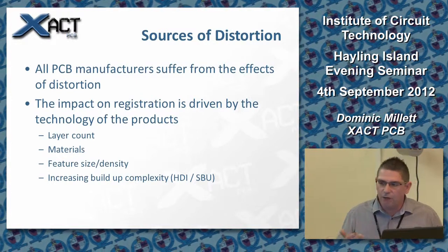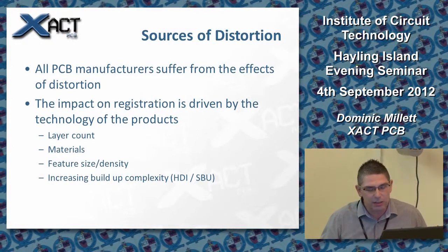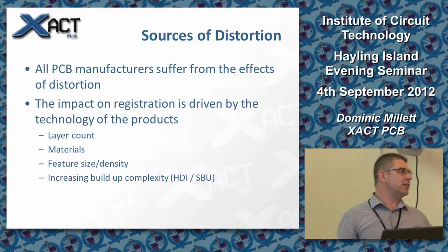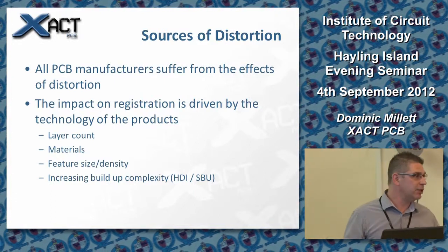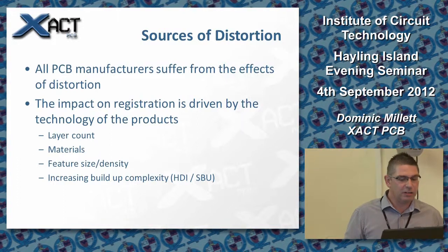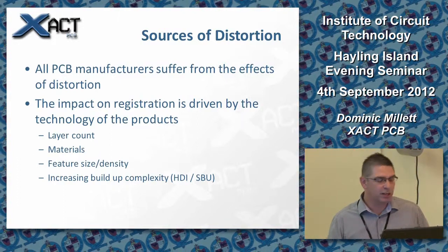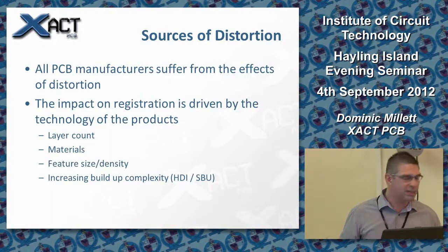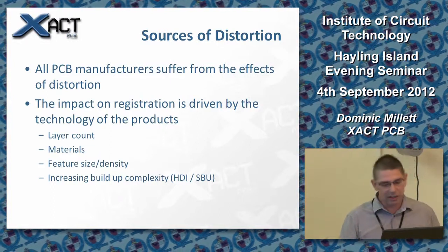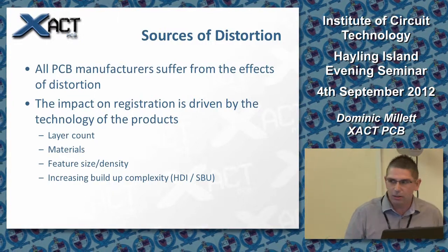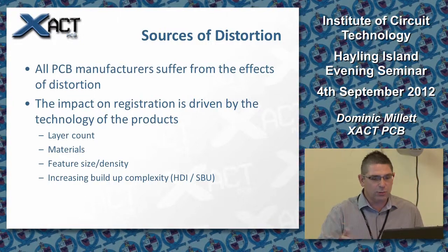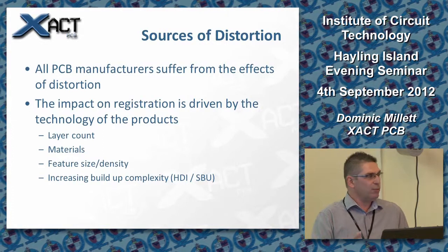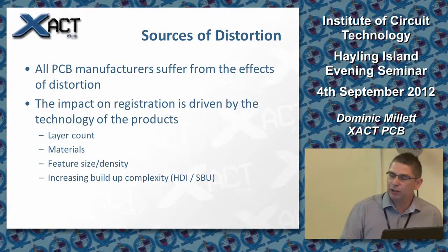Typically, we've seen a lot of designs getting ever more complex, not necessarily driven by a circuit design, but driven by chip manufacturers. They've changed the chip package, and then suddenly, overnight, the chip's obsolete. Designers have to design to the latest, tightest BGA. Suddenly there's another 6 layers added to a construction. They need to add microvias and buried vias. And the thing is, their customer doesn't want to pay any more just because he's designed a more complex board. It's driven by chip manufacturers.